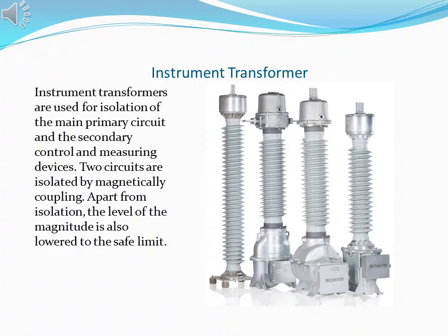Instrument transformers are typically used to operate instruments from high-voltage lines or high-current circuits, safely isolating measurement and control circuitry from the high voltages or currents. The primary winding of the transformer is connected to the high-voltage or high-current circuit, and the meter or relay is connected to the secondary circuit. Instrument transformers may also be used as isolation transformers so that secondary quantities may be used without affecting the primary circuitry.